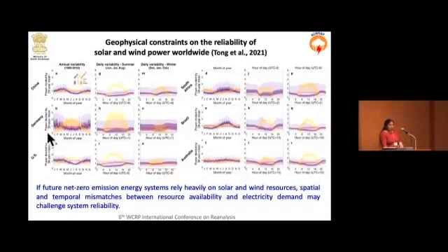If you see annually, as they reported, wind power is the reliable energy source. In the first column, the energy produced from wind is almost matching the energy demand throughout the period. Season-wise, we have the maximum sunshine hours during the summer, June, July, August, but again there is consistency in the wind power generation. In the winter season, there is a variation in the solar energy, meaning the incoming solar radiation and sunshine periods, but the wind power is again almost consistent over this location.